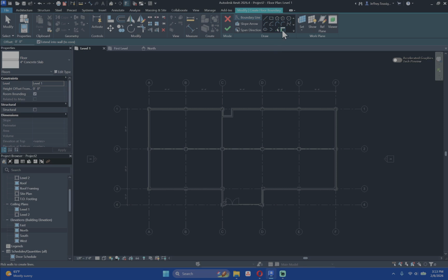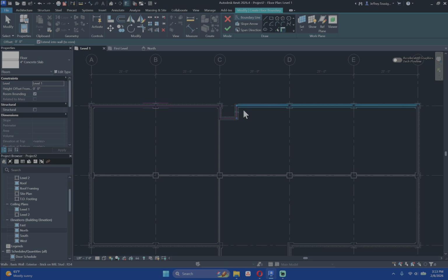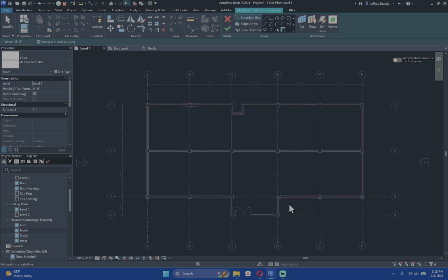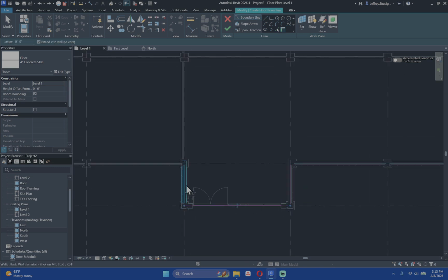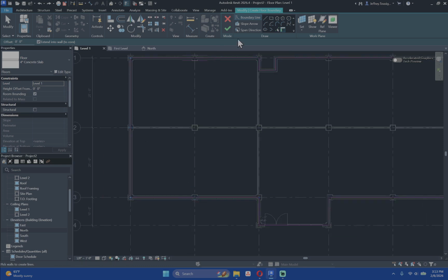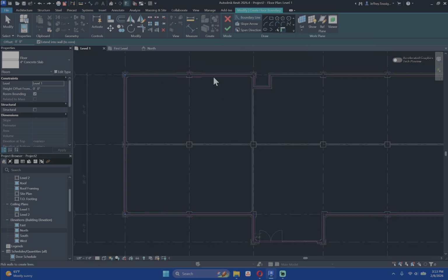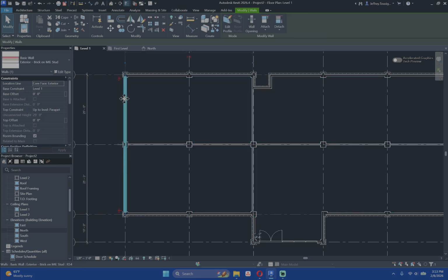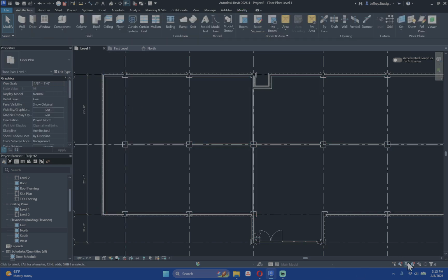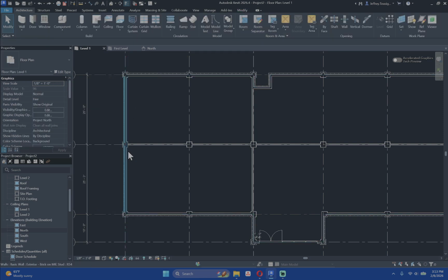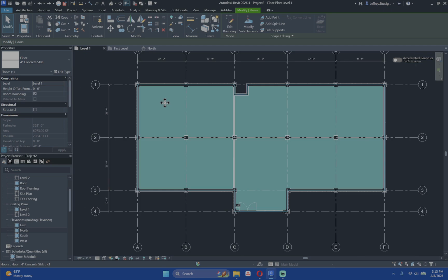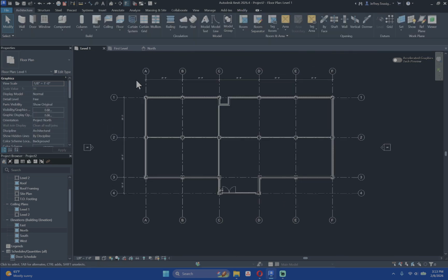And also, as I said, with the pick wall tool going, when we go around and pick our exterior walls, if we decide that these aren't supposed to be the locations of the exterior walls, that's why we are not using, I'm going to make sure to pick the wall, not the curtain wall. When we select pick wall, not just pick line, it is picking these walls. And that means if one of these walls change, it is going to update the floor for us. Maybe not other stuff, not everything, but at least the floor it would. So we can confidently put that in. And that's enough to get you started.